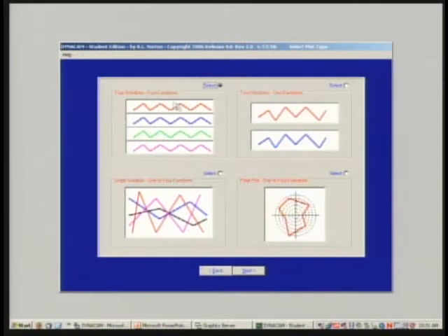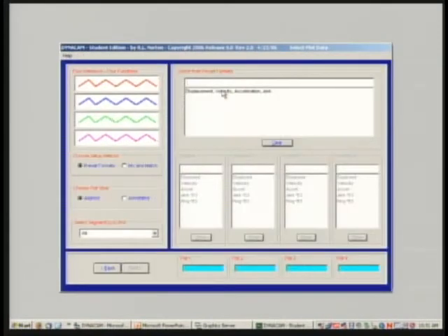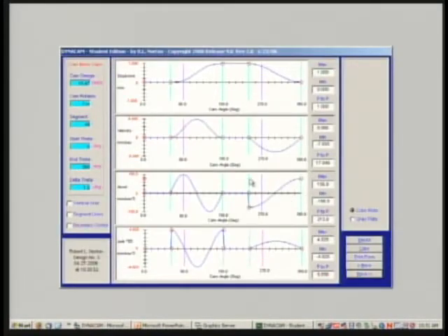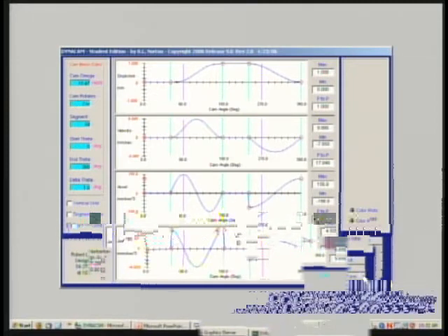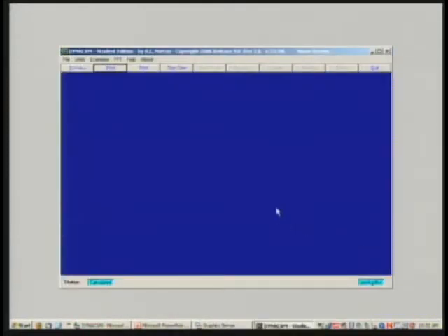If we go to the plot screens again, and I bring up this 4-plot business, now look at the acceleration here. Now there are two circles showing. That's a flag. The other circle didn't get drawn because it's actually over here. You can see them over here. This is the same point as this, right? 0 degrees and 360 are the same point. This is a red flag that something's wrong with your design. Acceptable in the jerk, but not in any of the lower derivatives. So I would reject this design and go back and change it to something else.